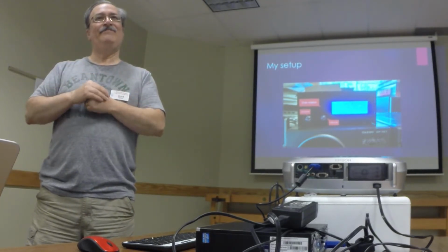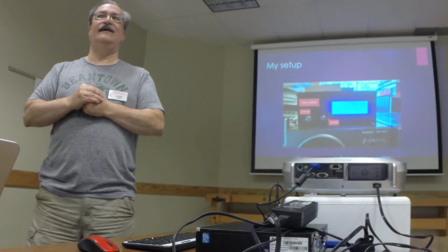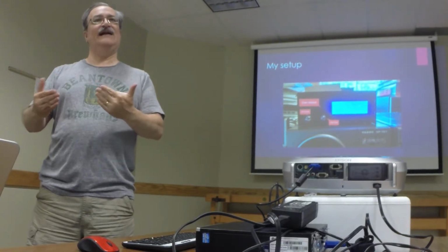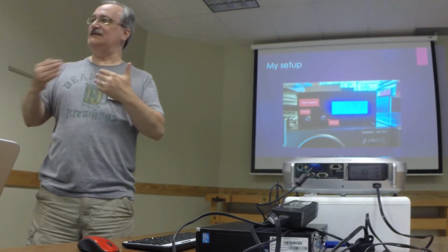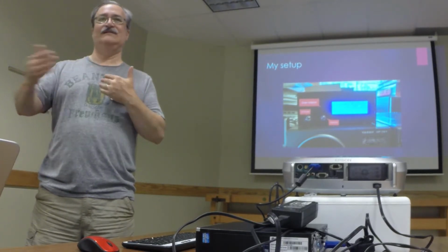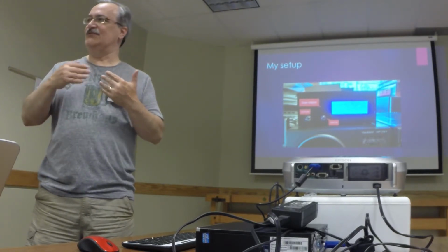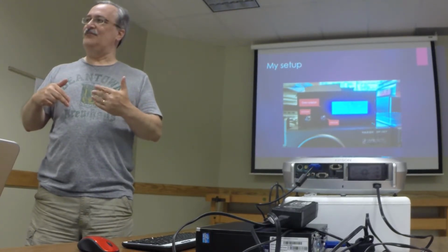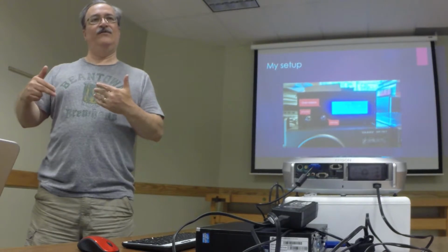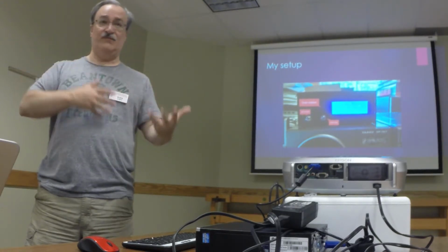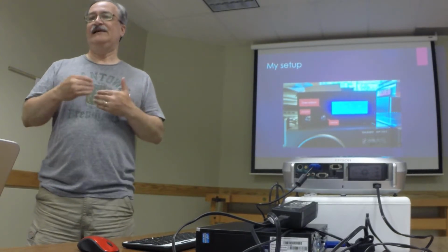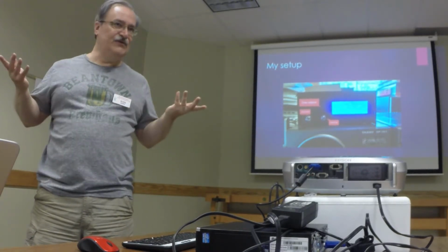Really low cost, simple. Yeah. And a lot of people have loved it. Well, to modernize that, I had to essentially do an opto-isolator with it, because there's a lot of 60 hertz that comes through that. So I opto-isolated it, brought it into a hardware interrupt pin, and then when the hardware interrupt triggers, it knows from configuration, and this is where the flexibility of the software comes in, it knows from configuration that means 10 degrees.